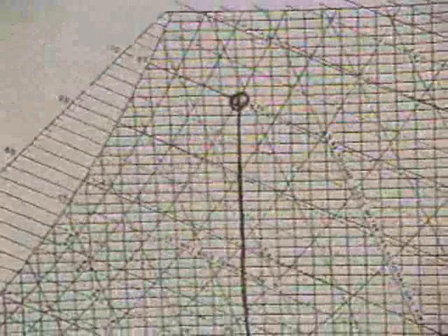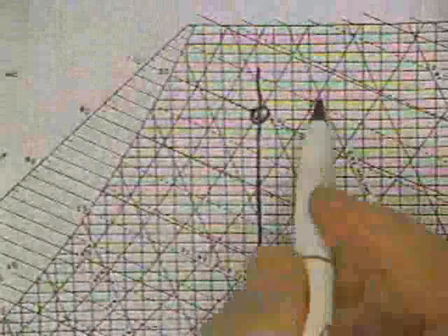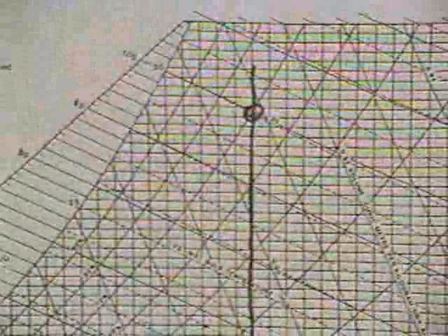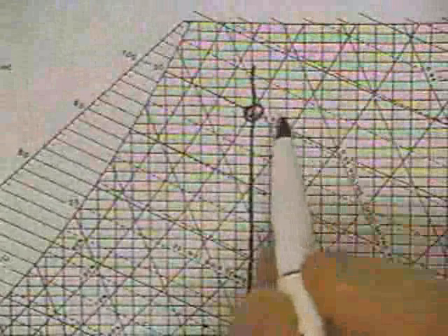The 70% constant RH is this curve that goes along here, and the dry bulb temperature of 35 degrees C is where we start, intersecting with 70% RH. So we have a very high moisture content. However, this is something that we can read directly off the chart.